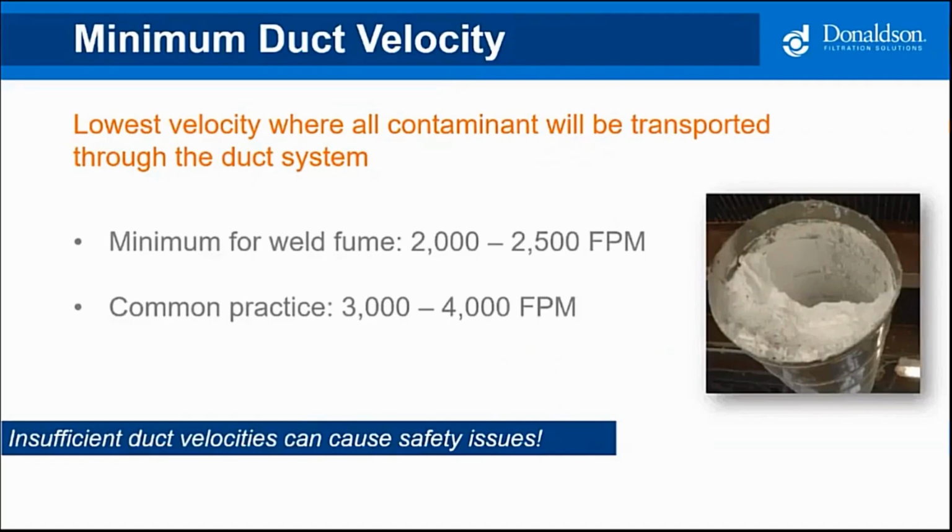Okay, so once again, let's revert back to the Industrial Ventilation Guide that I mentioned. What are the proper variables? Again, I've seen so many people walk in with an HVAC background, and of course, they understand the physics of air. They understand the flow rates, and they design, but the conveying velocities in an air conditioning duct that's moving air that has very little dirt and dust particulate in it is typically designed around 800 to 1,000 feet per minute.